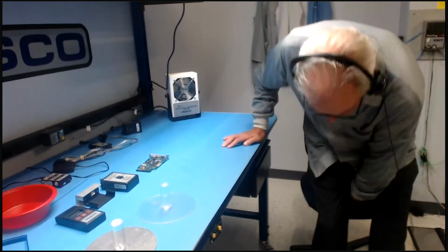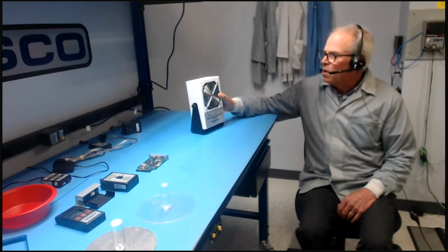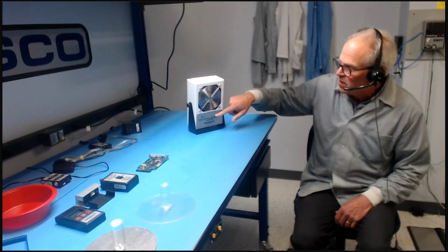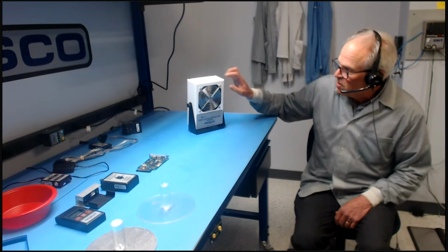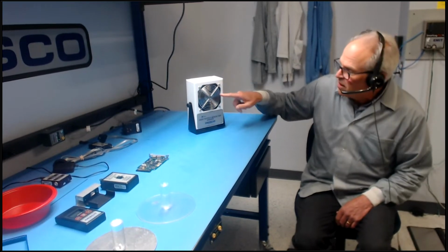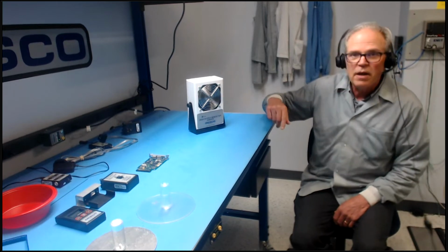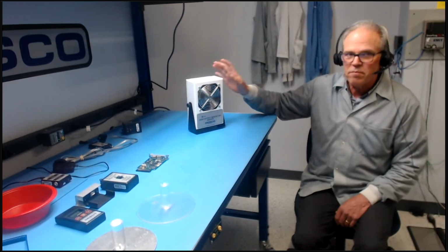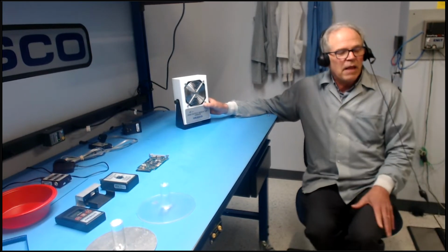how they work. An ionizer, this ionizer, for example, takes the 110 line volts. There's a step-up transformer inside, steps it up to 3,000 to 5,000 volts. The high voltage goes to these emitter pins that are in here. The camera's not good enough for you to see them. And the ions are created, and then the fan blows them out. That's basically how they work.